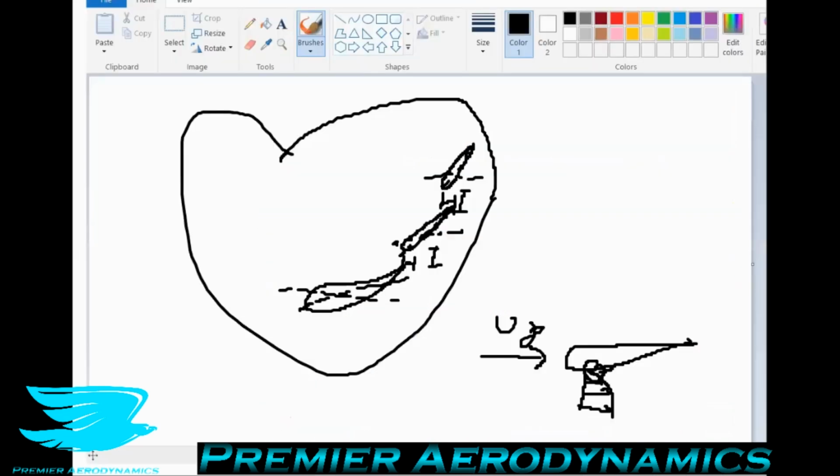So why is this important? I should actually mention this a little bit more. The reason is because the flow coming from one airfoil, I've actually drawn this a little bit poorly, and I'm going into it a little bit later. But anyway, the flow going over one airfoil will now go over the other airfoil and be redirected. So now you can get this entire system producing a lot of lift.